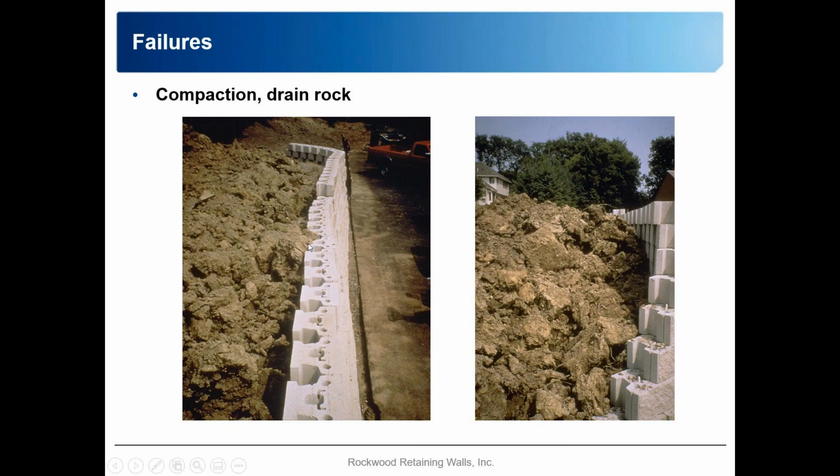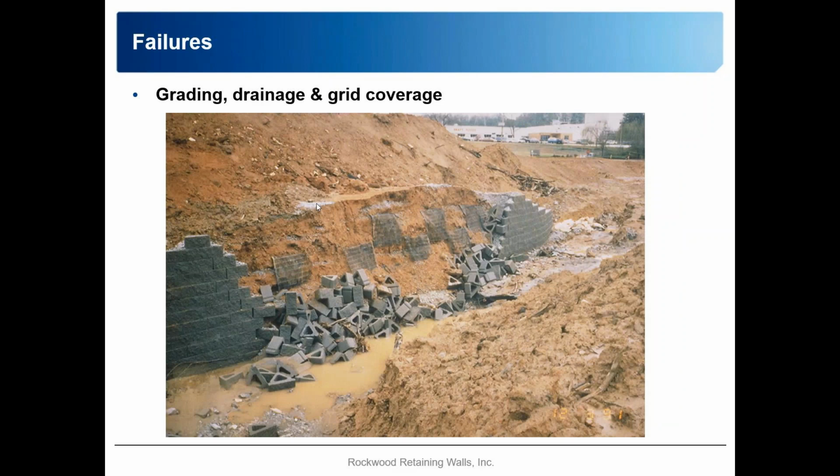We have fat clays right against the back of the block, material that was never placed or compacted correctly or properly, and you can just about guess what's going to happen when water or a rainstorm comes in. All of this is just going to flow right out the face of the wall. This is actually a very dangerous application in a fairly tall wall. So it's a wall that hasn't failed yet, but it doesn't have much of a chance of being successful.